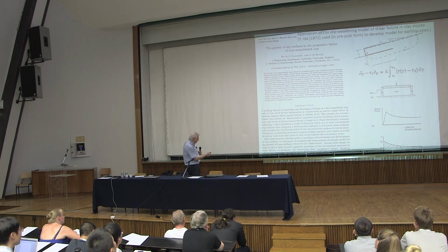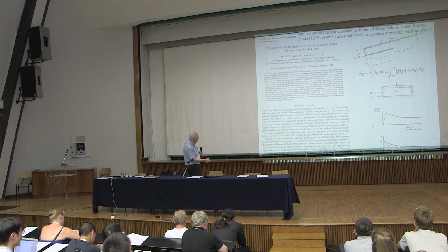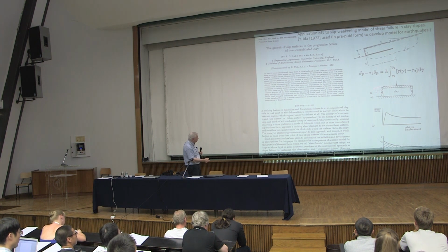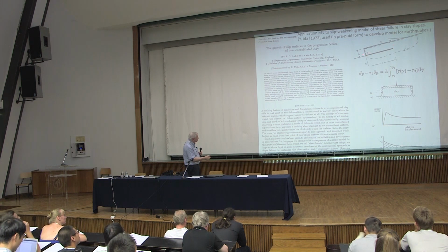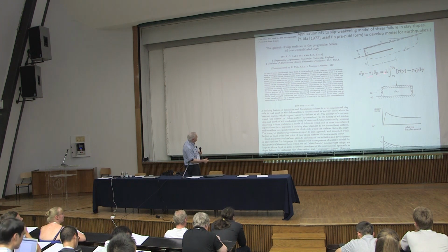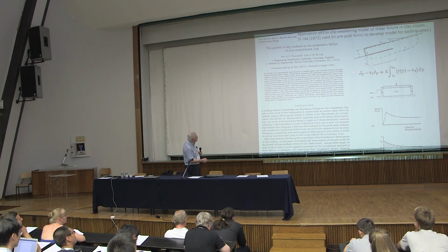So this shows the path of a path-independent integral around such a mode 2 shearing crack. And the evaluation of J from things that you could measure from a direct shear apparatus for homogeneous deformation before the onset of localization. And that gave us this formula here, where the tau sub r is a residual resistance on the sliding surface.